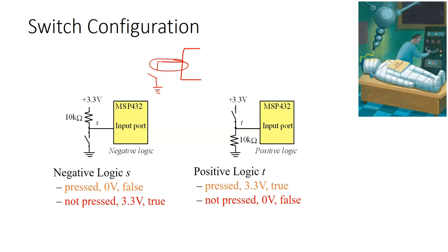For this reason, it's always a good idea when you're not using GPIO pins on the microcontroller to put them into a non-floating state, either setting them as outputs or connecting them to a pull-up or pull-down resistor, which we'll talk about in a second. You've all probably seen a warning when you've compiled in Code Composer Studio about having pins left in this state.